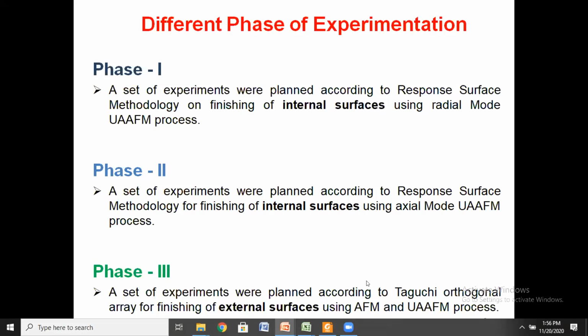If I want to conduct fewer experiments while varying more parameters, then I choose the orthogonal array L9. For example, if anyone is working on friction stir welding of steels using a costly tool, which is used for joining the steel materials, then probably you cannot do a large number of experiments.